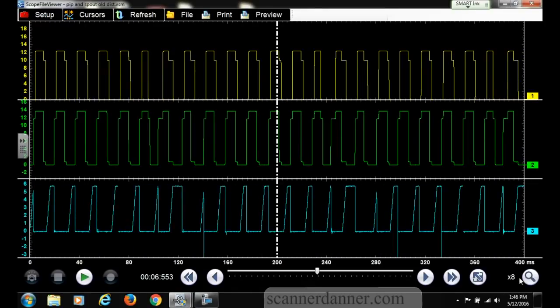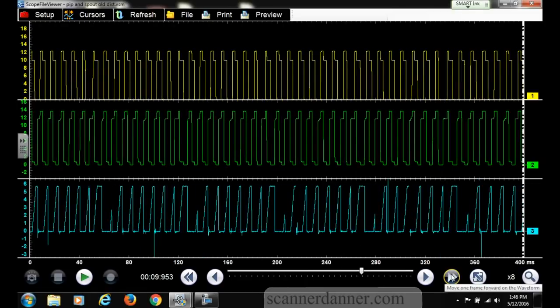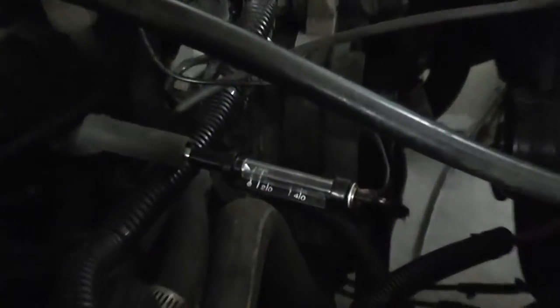See the difference. See why this vehicle was misfiring. Even you guys that just came in would be able to tell by looking at the blue trace why this thing was misfiring. Let me get to a different section where it really emphasizes it. We had a number 2 cylinder that the spark plug kept dropping spark from. We did a visual inspection. When I have this all together, you guys that were doing other projects will enjoy this because you'll be able to see physically, I'm showing the spark is missing from the number 2 spark plug wire coming right out of the cap. And the majority of people in the field would put a cap and rotor in it for this problem.